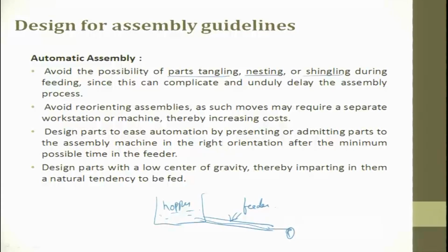So what we have to do is, when we are taking parts from the hopper and pushing them, the parts might get tangled, the springs might get tangled. So you try to make sure that the parts do not get tangled, nesting does not happen, and shingling does not happen during the feeding, since it can complicate and unduly delay the assembly process. Avoid reorienting assembly, as such moves may require a separate workstation or a machine, thereby increasing the cost.